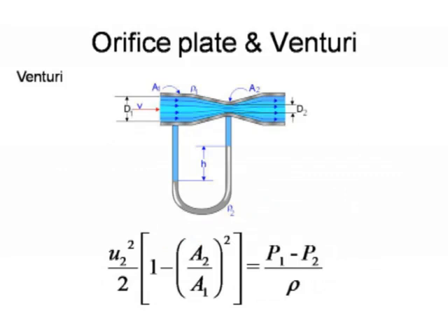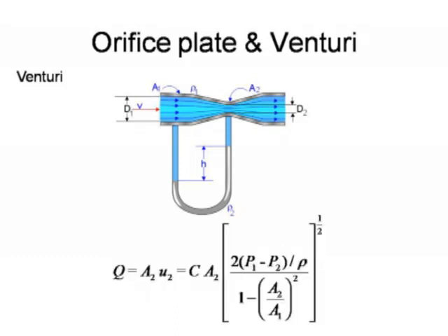Well, we've rearranged the equation here, having taken pressure over to the right hand side and velocity is all on the left hand side. We've made our substitution, removing u1, having used continuity. So on the left hand side all we have is velocity in terms of u2, the velocity at the constriction. And now we've rearranged the equation so that having obtained the velocity u2 on the left hand side, if we multiply it by the area, then that gives us the total volumetric flow rate.